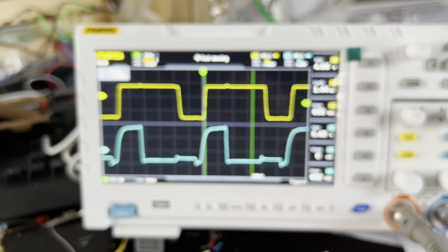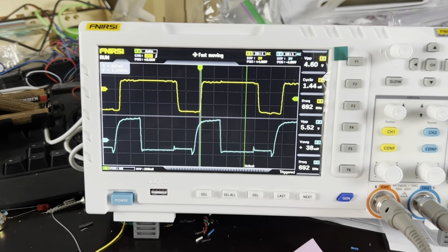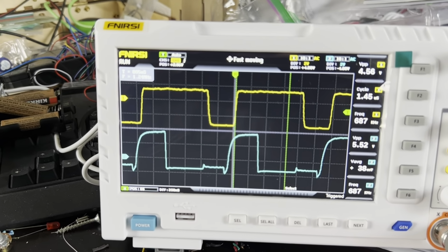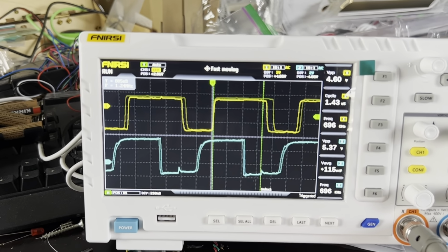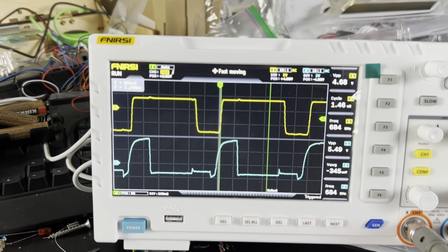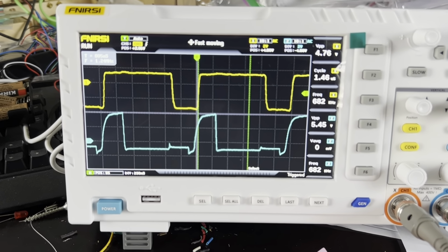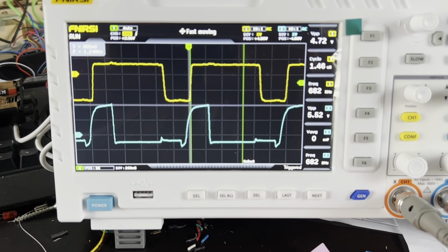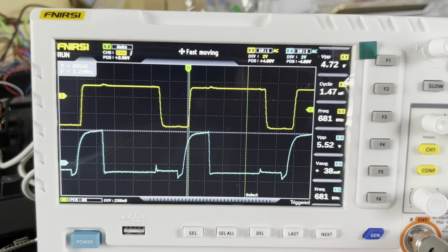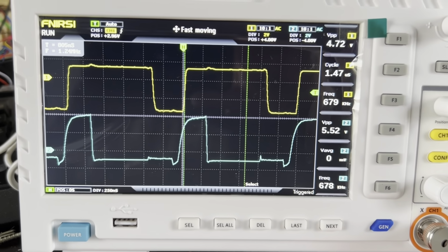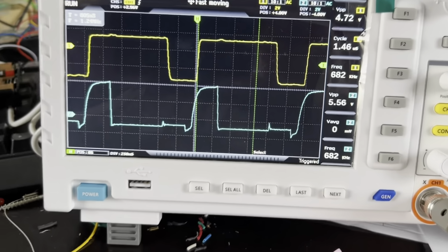And now, if you could look at the way the signal comes out, the leading edge is now in the right position. The leading edge starts when the other leading edge happens. So, you know, any deviations from this are probably breadboard related, but now you can see it measures about the same. Let me adjust the clock a little bit.